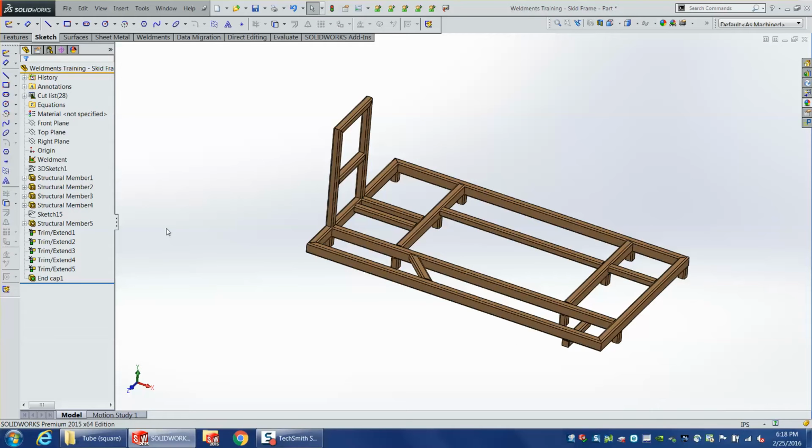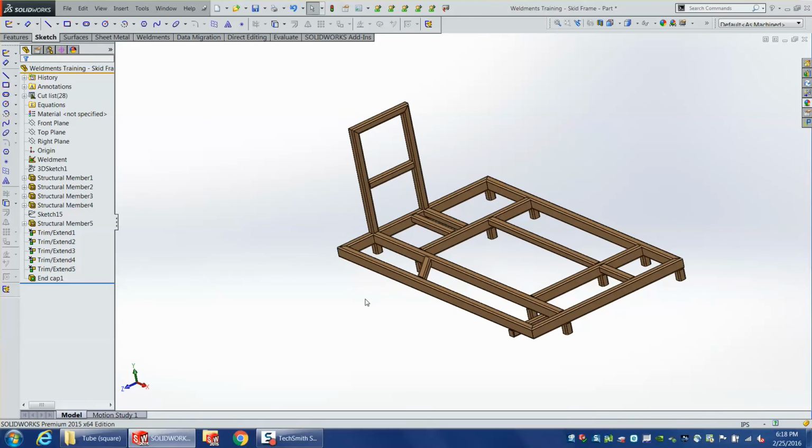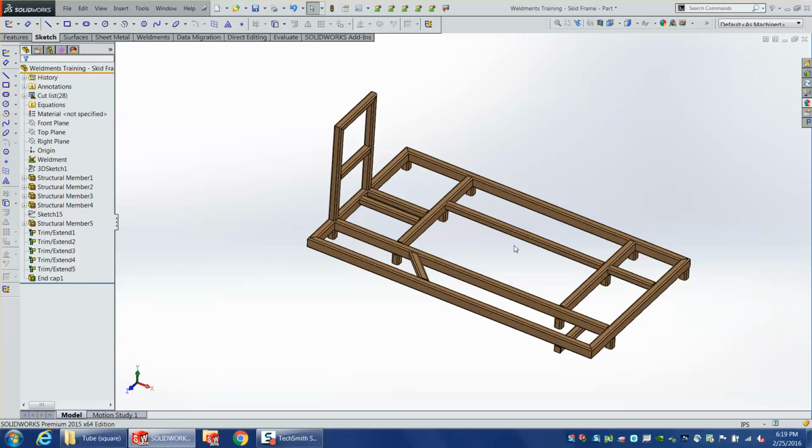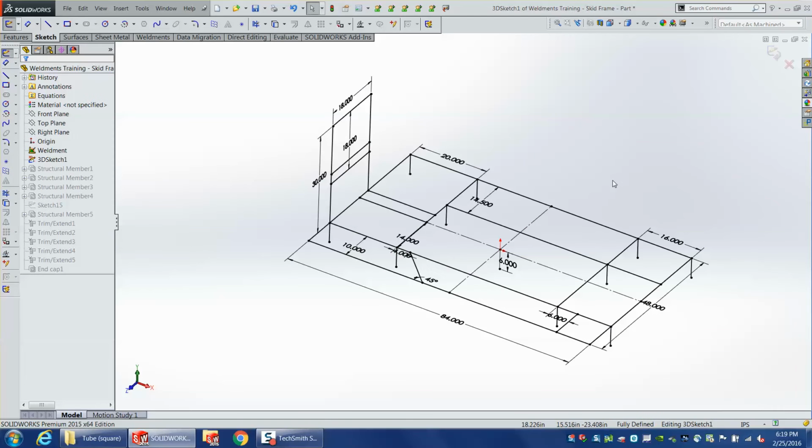Resist chain constraints. So if you do a 3D sketch and you select 6 lines at a time and you say equal, it's going to set one equal to the next, equal to the next, equal to the next. And this is a problem because if you delete the middle one, now you have a break in the chain. And you're forcing SolidWorks to solve it in that order. So if you set them all equal to the one original line, then you have a more robust 3D sketch.